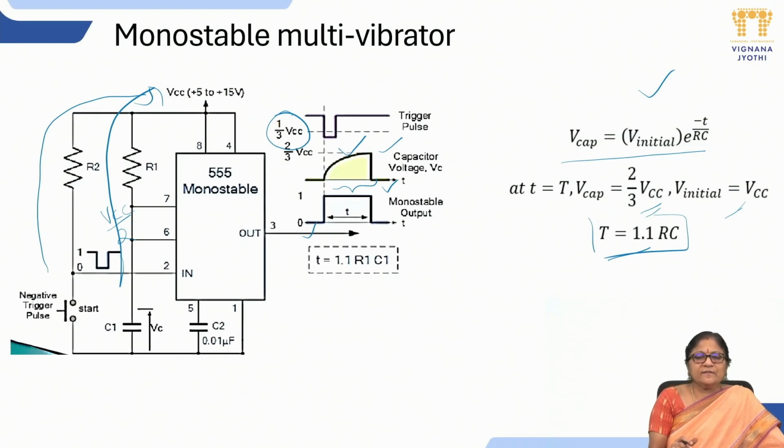Basically, it is used to trigger other circuits like an astable multivibrator or any other device where you want the on and off of that particular circuit under user control. So the user uses this trigger pulse. Maybe this can be used as an alarming signal when building applications like burglar alarms, theft alarms, or fire detectors. This can be used as a trigger pulse so that whenever it triggers, it gives out a pulse which is used as a warning pulse.